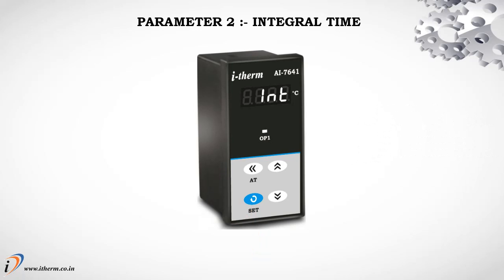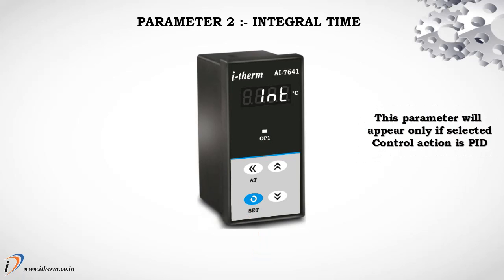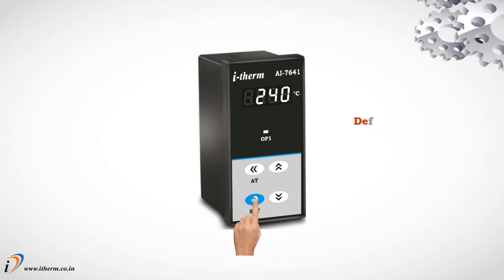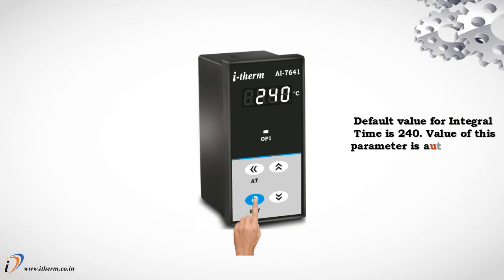Parameter 2, integral time. This parameter will appear only if the selected control action is PID. Default value for integral time is 240. The value of this parameter is automatically set by the auto-tune function.